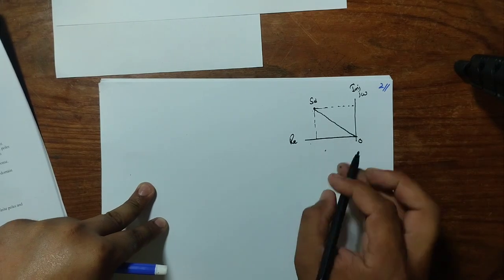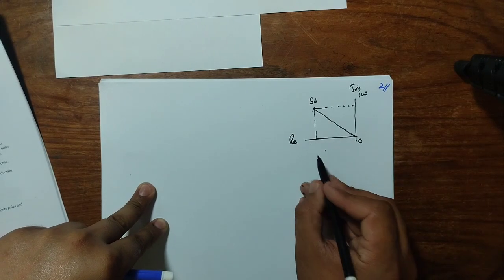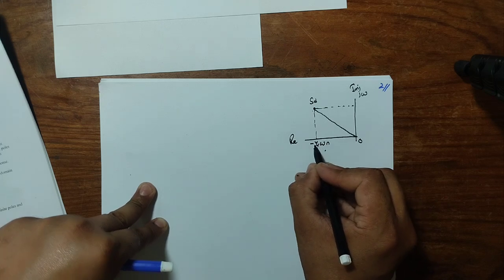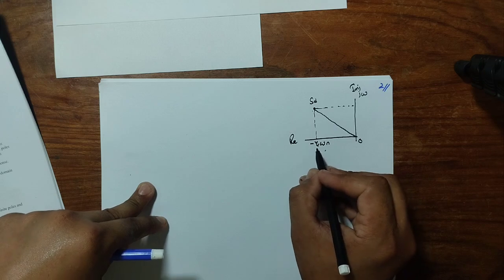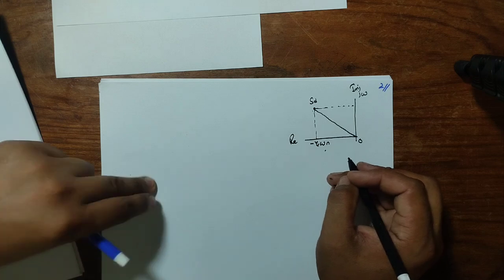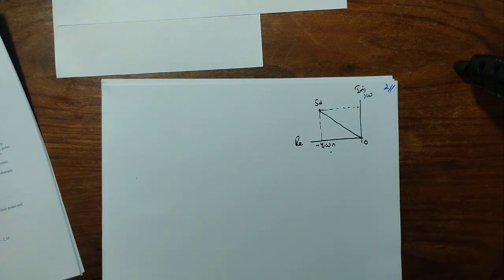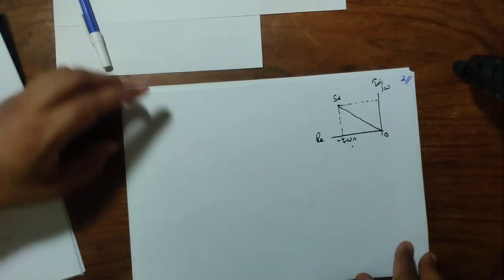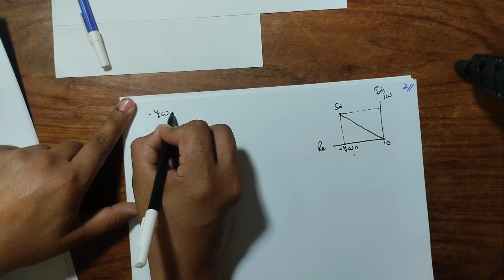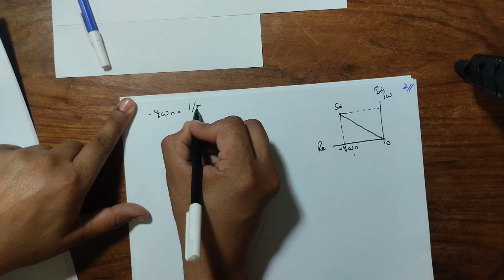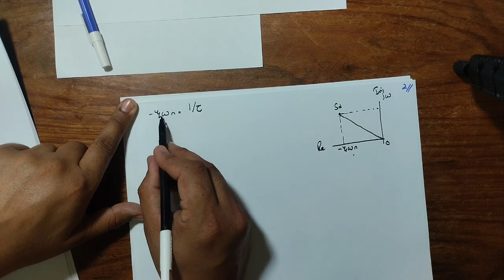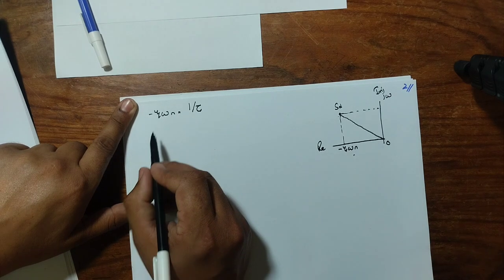As we know, the real part of any pole has the real contribution of minus zeta omega n, where minus shows that it is a left half plane value, and zeta omega n is the real part of the complex root that we normally know. From the earlier chapter number 4 in this book, we know that the real part has an indirect contribution towards the time constant of the system. So tau, the time constant for the system, has an inverse relationship with the real part of the complex pole.